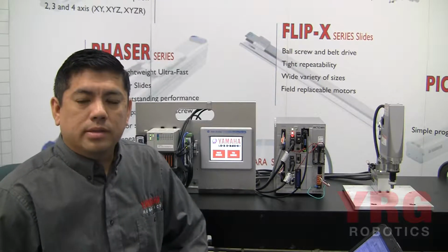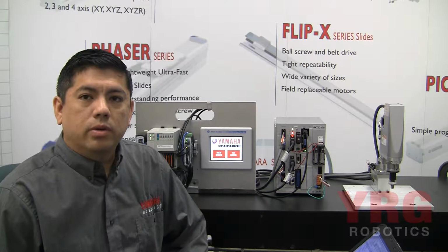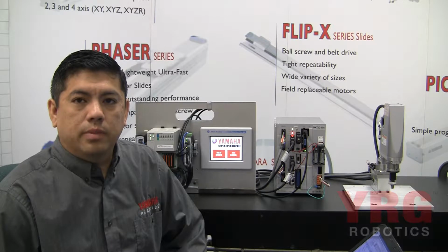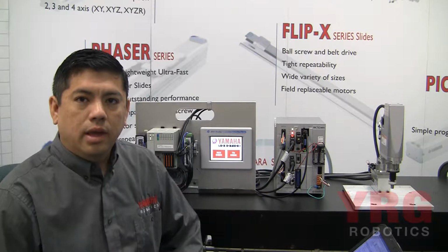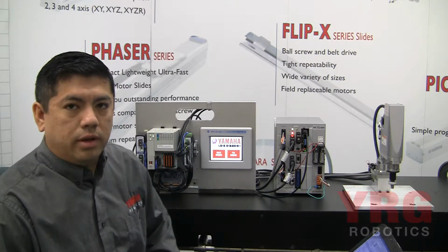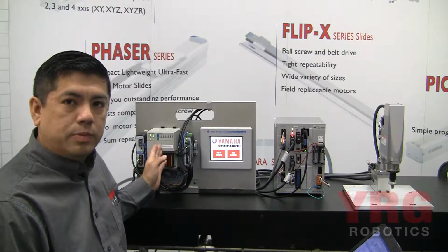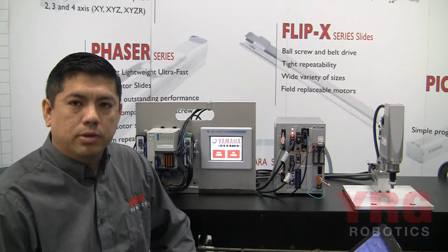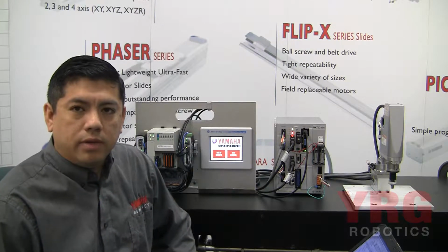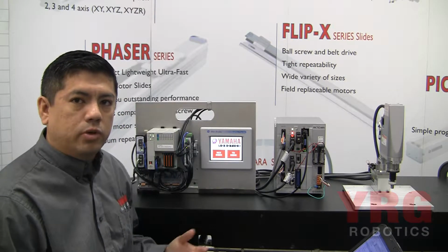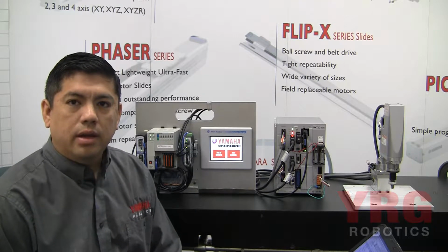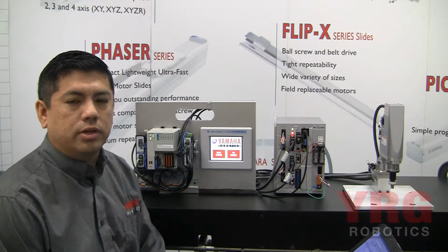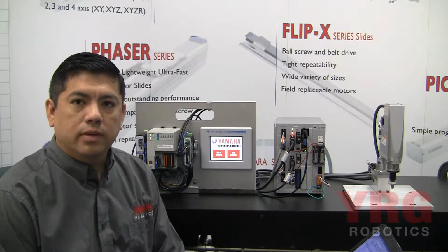From Yamaha Robotics, and today I want to talk to you about our new Allen Bradley LadderLogix integration concepts that we've developed here at Yamaha Robotics. Behind me I've got an Allen Bradley L1 CompactLogix PLC. This is the lowest cost CompactLogix that you can purchase today. It doesn't have SIP motion in it, so what I'm going to be demonstrating today is the ability to communicate from a CompactLogix directly to our RCX 240 controller via Ethernet IP.